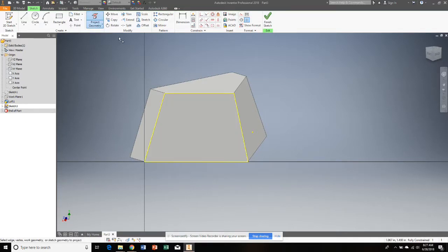box. I'm going to come over here and choose the tool Offset. I really like this tool because it allows you to grab things and multiple lines, and you can move them and they all move together. I want this to be offset a very small amount. I need it to be offset only 0.1. Now I set that down. That was probably a mistake. I'm going to hit undo and redo that offset. Pull it down and say 0.1, enter, and there's my offset.